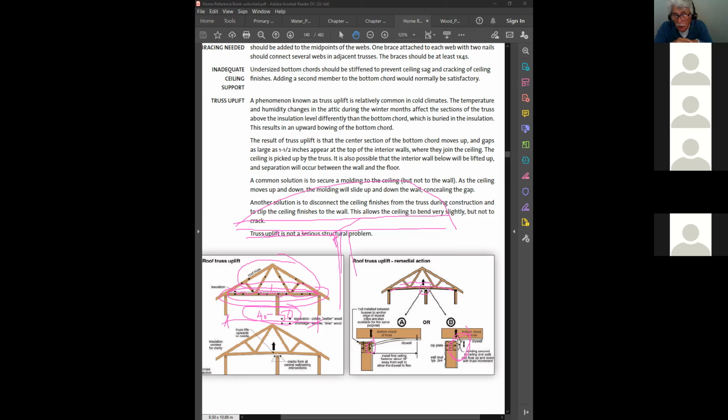So in other words, do I take this into consideration when I'm building a roof truss? Well, depending on the span, okay? Depending on the span, if it starts exceeding 40 feet, I will tell the architect, all your walls that are coming to the underside of my trusses, don't attach them. Give them this detail.